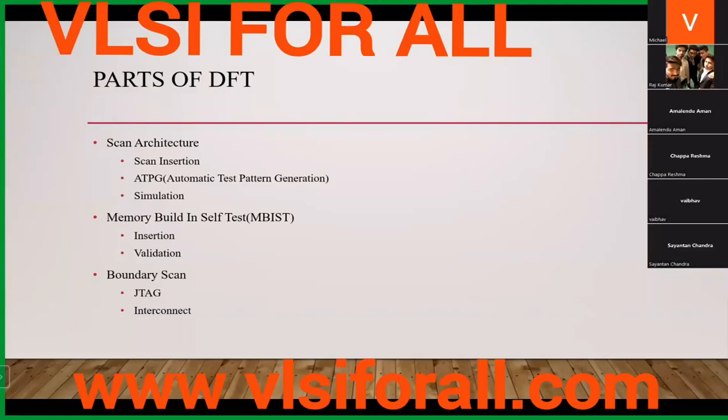MBIST is basically a built-in self-test. Memory testing is very different from scan testing, because one reason is that the memory architecture is altogether different, and the type of work we want to do through memory is different. We only want to put a 0 or 1 on a memory. We don't want any logic to be calculated or any complex architecture. Memory is only reading from memory and writing into memory. So we have very different types of tests for that, and we call it MBIST.